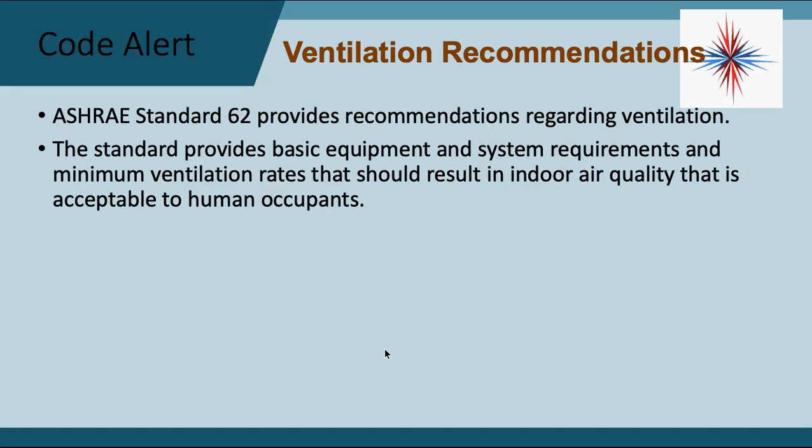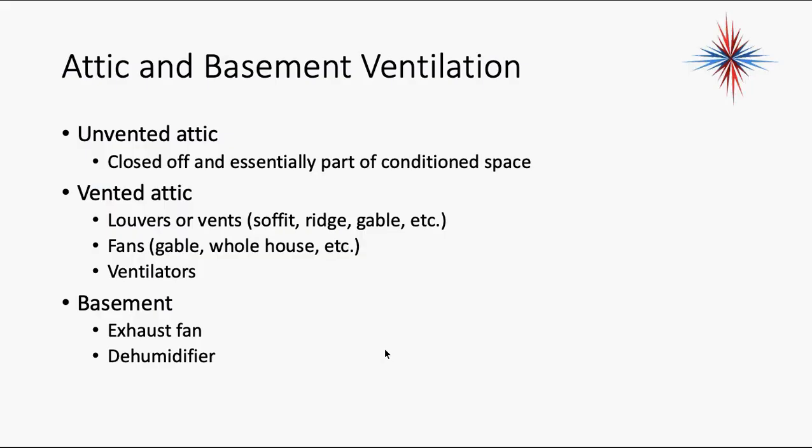Surprisingly, the worst air quality you can find is in assisted living facilities, where a lot of our elderly end up. That is by far the worst air quality you will ever find, and that's because they're on a fixed budget there, and the owners of those buildings a lot of times start to cut down outside air. That's the first thing they cut down when they realize what their cooling costs are. So that's something always to keep an eye on.